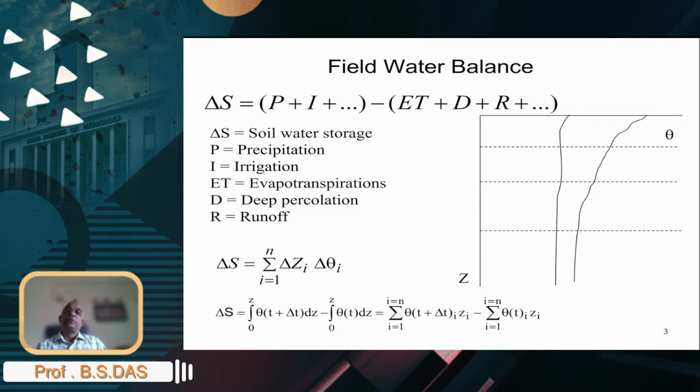Anytime the addition of water exceeds the capacity of the soil to infiltrate, the excess water is going to run off in the form of overland flow. Water may also leave a control volume of soil through lateral flow in the form of seepage.